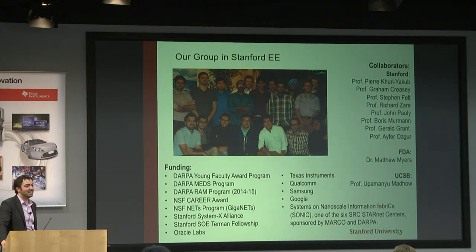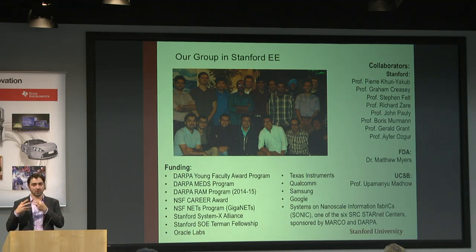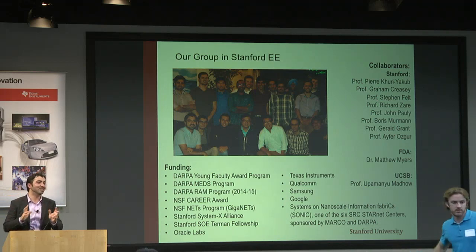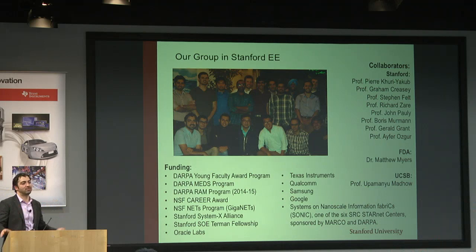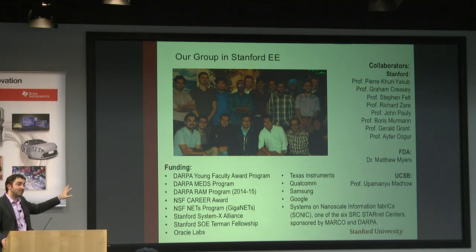That's real time because we're not doing anything very complex. This is a layered SAR reconstruction. The beauty of frequency domain SAR is that if I do a time domain SAR, I need all these filters at different points. Frequency domain SAR is nothing but an FFT. We make it sound fancy and say frequency domain SAR, but we're running FFTs. If you do layered SAR, you run FFTs plus boundary conditions, so it is as fast as you see. It's even perhaps faster, but it's not as accurate. So you saw there were ghosts on the targets and things like that. That's the problem. Yeah. Great, thanks.